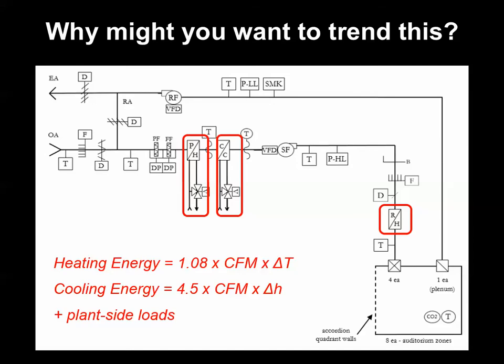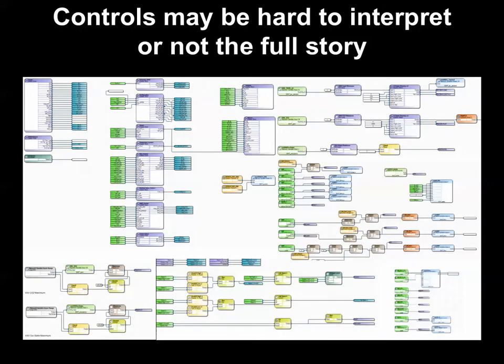So one valid question may be, why not dig into the controls and find out what's happening? And as we said during the HVAC fundamental lessons, being able to read logic and understand control systems is a key skill. However, in many cases, a clean view of operation may not be possible. And even where you're able to correctly assess and interpret control logic, there may be other factors at play. For example, in this case, possibly a preheat valve failed or leaking.